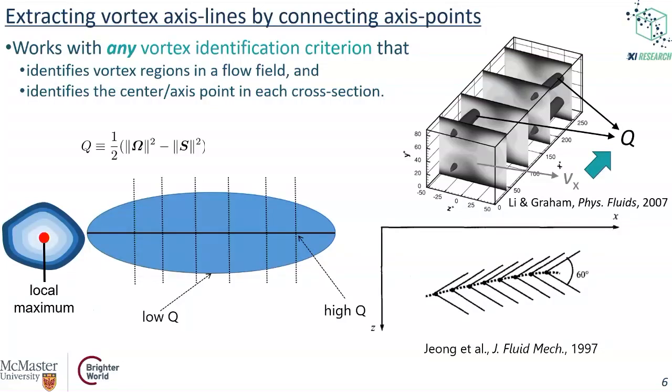The problem is that back in the 90s, if you remember, there was a lot of interest in those pairwise streamwise vortices, right? So the vortices of interest back then were mostly linear or quasi-linear. So this method works very well for quasi-linear vortices. And it starts to break down, obviously, when you start to get interested in hairpins and more complex three-dimensional vortices. And that's where we start to jump in.